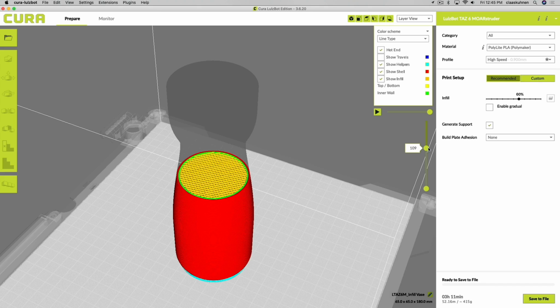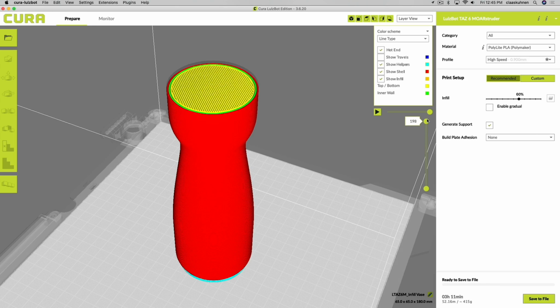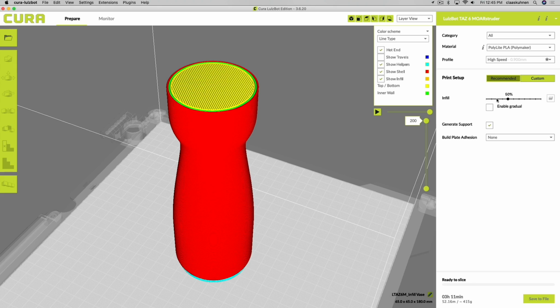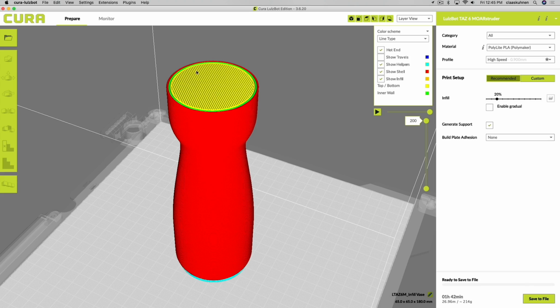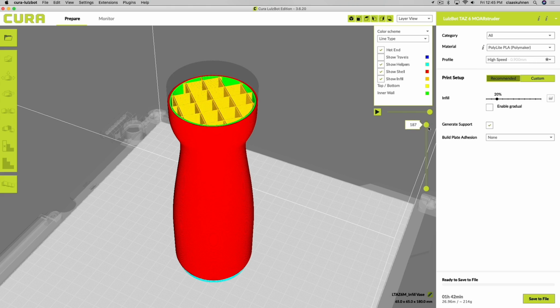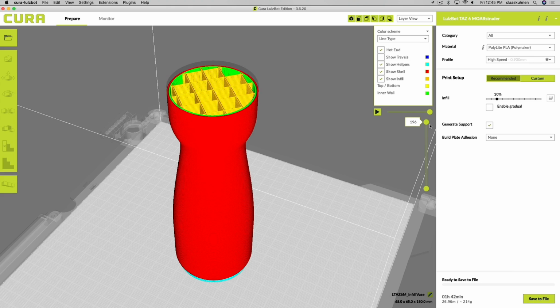And in this case, when I want to print a solid piece, I also need interior support for the top to be printed. That essentially is what the infill allows me to do. Sometimes I have to adjust the numbers for infill to make sure on very big horizontal surfaces it is nice and smooth and not having issues with the plastic falling down.